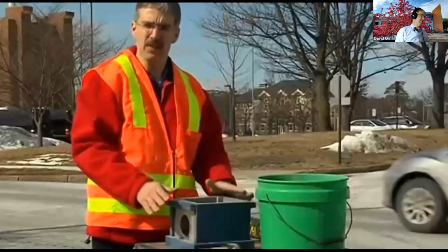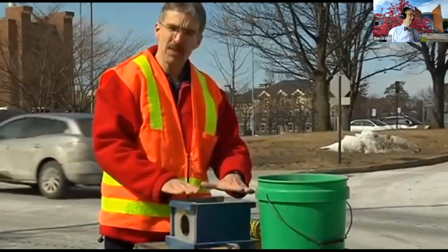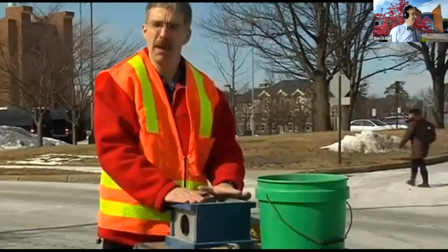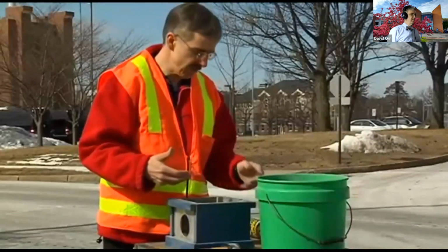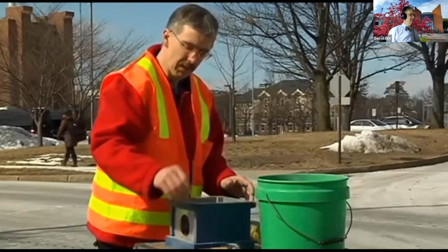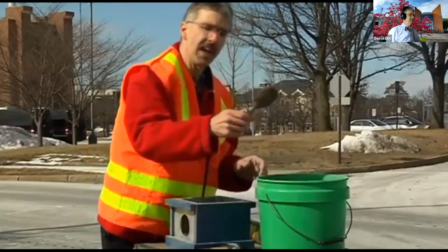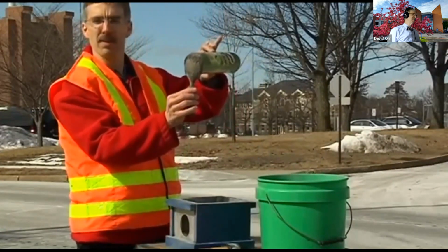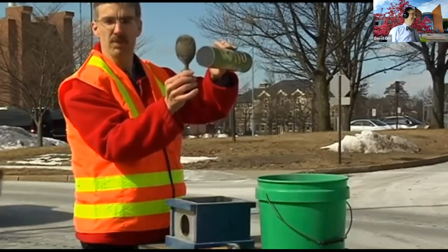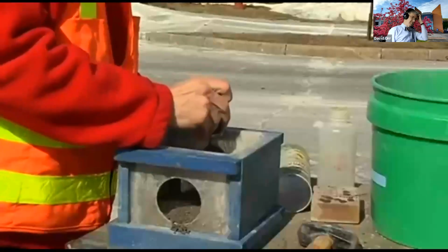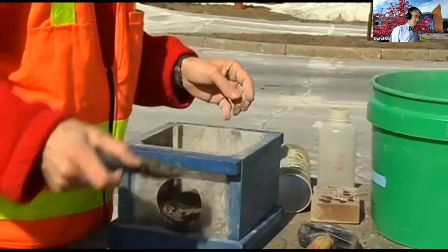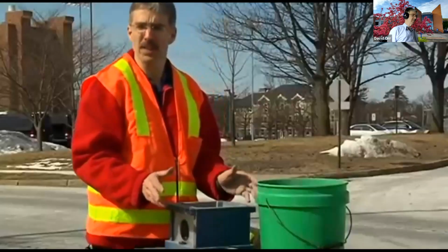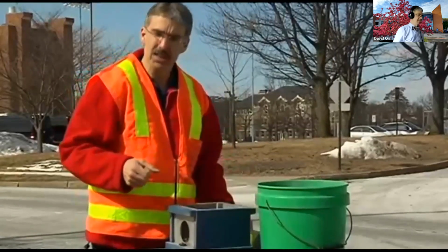Now I put in a second lift of gravel. I'm slightly above my final elevation for my pipe. I'm not doing that because I'm worried about the pipe settling. I'm doing that to provide a place for me to lay my pipe in as a haunch. What I'm going to do is dig out a little bit of a space to do that, and I need something the same shape as my pipe. In this case, my little tool does that. But in the real world, you could use a collar for your pipe. That works just fine. It's a great template to set the shape of your pipe.